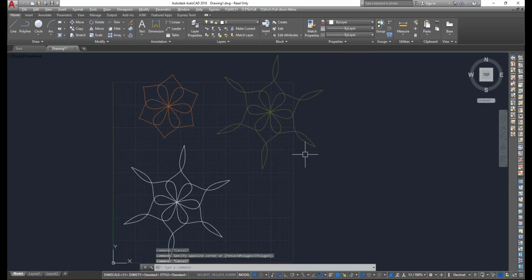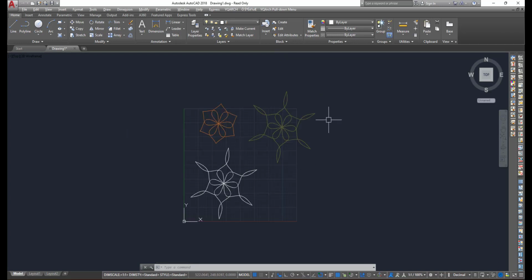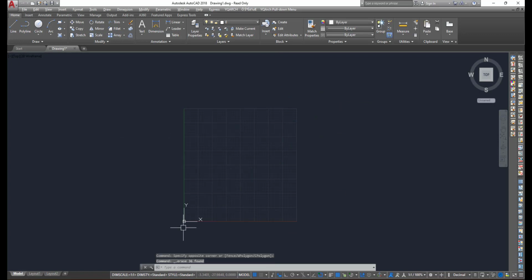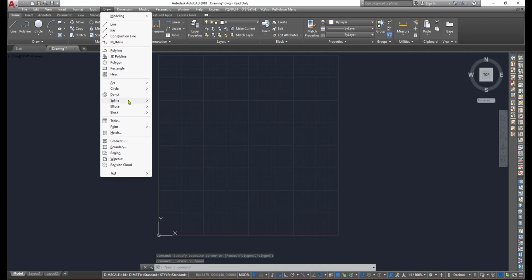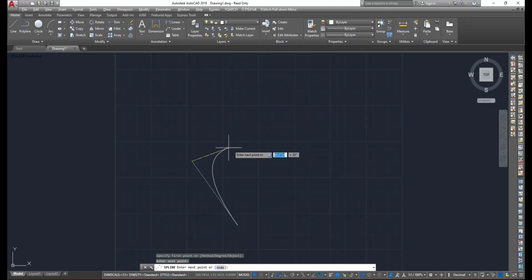So like this way you can implement the spline command while doing the interior design or door design, anything, whatever you want. I am selecting all by pressing Ctrl A and then delete. The next method is spline with CV. It is also the same, but I am getting extra smoothness from the clicked points like this. So you can repeat the same process as earlier.